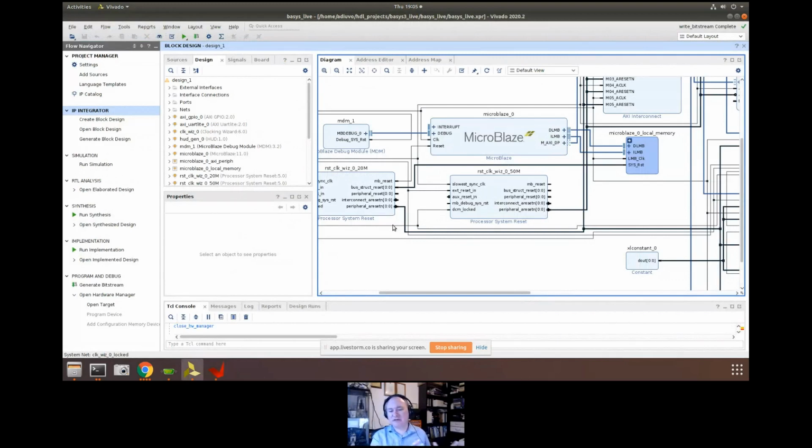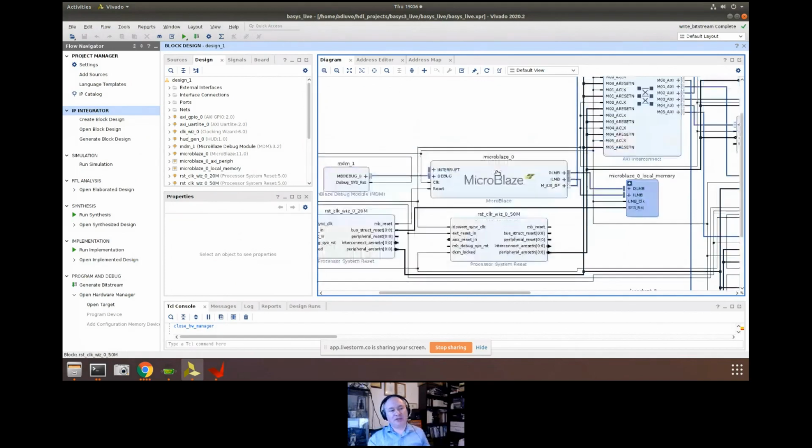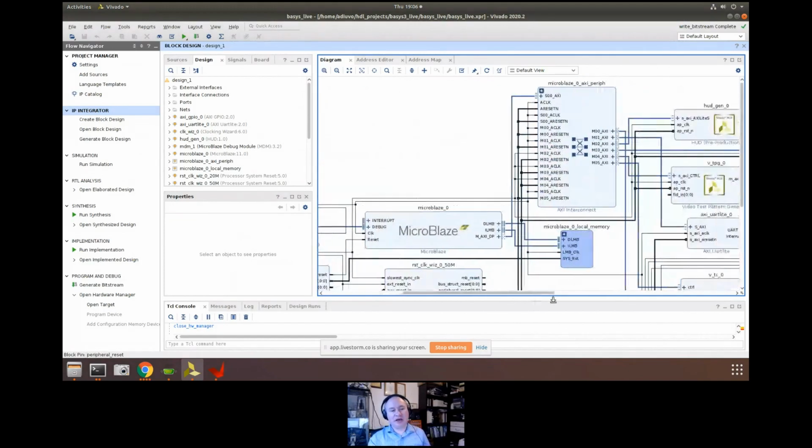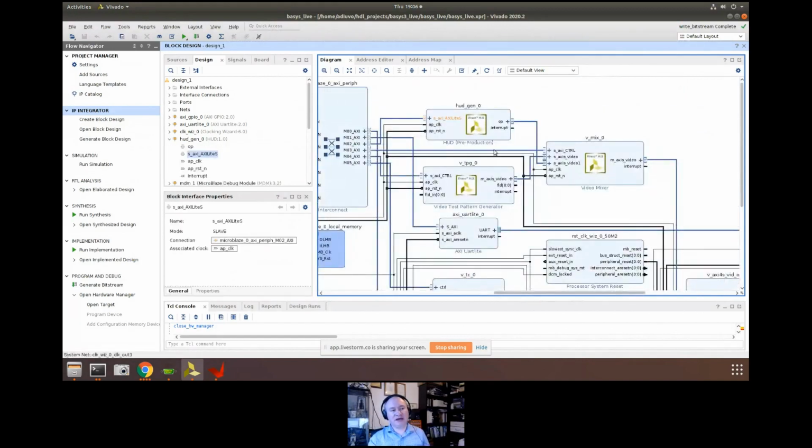The only difference to that is if we were to use high-level synthesis, then we would use Vitis high-level synthesis to take a C or C++ algorithm and compile that into an RTL description that can be pulled into Vivado. You can see that in this example, and the HUD generation. If you take a look around the GitHub, you'll find all the code for that HUD and for everything else is available on my GitHub as well. So you can take it in, run through that, and explore that to your heart's content.